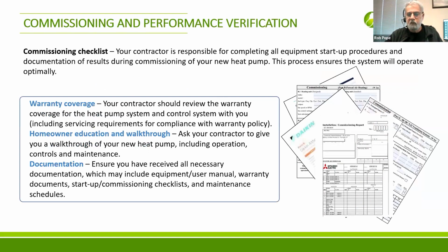Commissioning the system. You can't just turn it on and walk away. You've got to test the system. We have to measure the airflow: are we getting the right airflow? Measure the pressure drop so that you can make sure your fan speed selection is correct. You've configured everything right and the controls understand each other. There are no leaks in your refrigerant, no leaks anywhere.